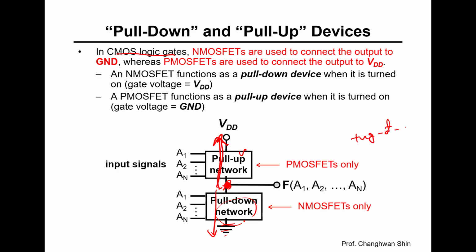The N-channel transistors are team members who pull the rope downward toward the ground, while P-channel transistors are team members who pull upward toward the VDD power supply. The winning team determines whether the output is high or low. The beauty is that we never allow both teams to win simultaneously in static operation, as that would create a direct path from power to ground, wasting energy, right?